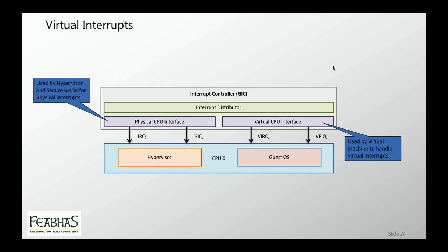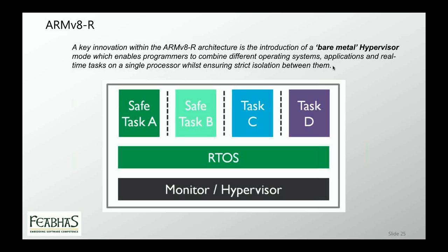One thing to be aware of is that ARM announced, as part of the Cortex-R family, which has been heavily utilized in the automotive industry, that on the new v8-R series there is going to be hypervisor technology support. So this will give us safe tasking and this isolation model, again along the lines of the ARINC model. So we can start to have guaranteed hardware separation, but in a real-time area as well. It's worth noting that for the ARMv8-M, the TrustZone technology utilized there is not hypervisor technology. It's purely a trap model.